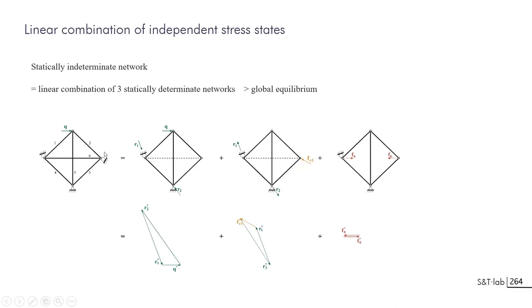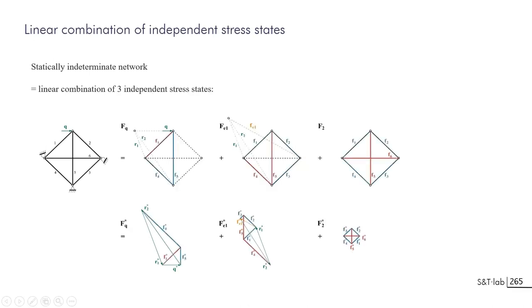And actually, what has been done with applying force can be connected with the force that was applied on the previous slide. So in the end, such a problem would be a combination of self-stresses 1 and 2, and the stresses coming from the applied forces here, and your result can be tuned in that way. The fact is that if you remain in elastic analysis, you have to tune all these forces to fit the equilibrium of the structure together.